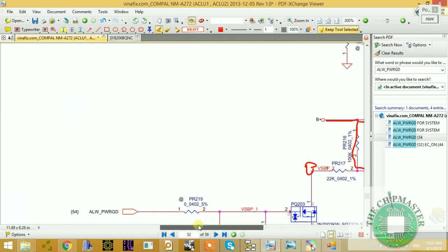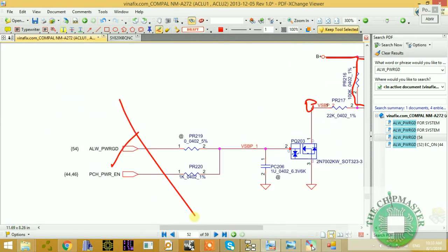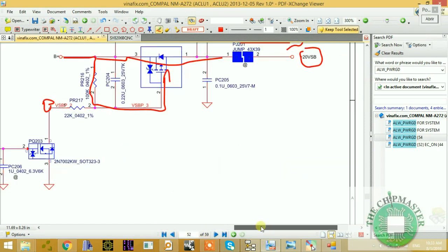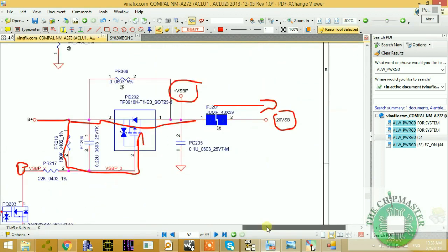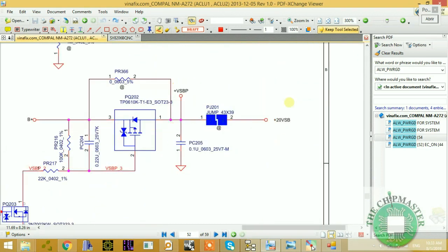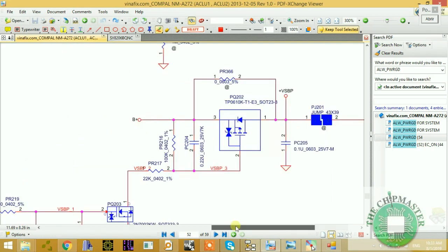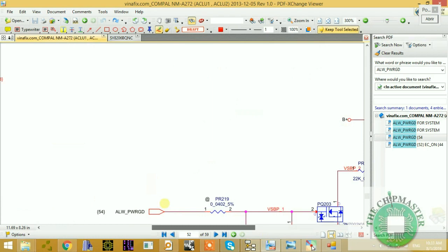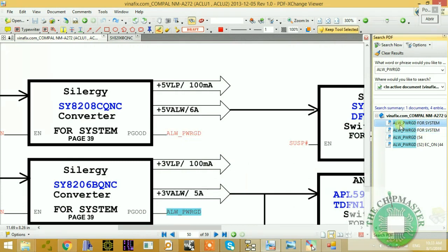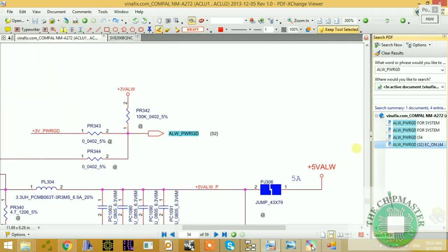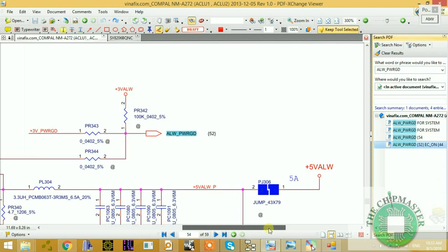So if this power good signal is not coming, then your laptop will turn on and then shut off, or power on without display. So this is a critical voltage that you should check. Many times this voltage will not be present, maybe due to water damage, or a broken pad, or a fault on the 3.3 volt rail regulator section, and the voltage won't come out. So the power good signal is critical that this voltage comes out, right?